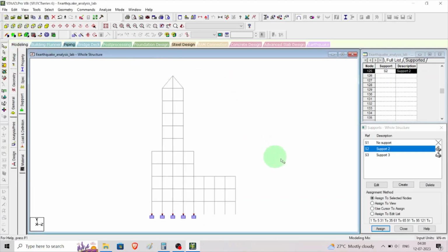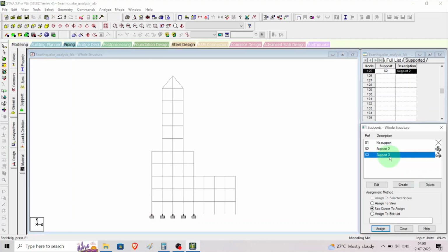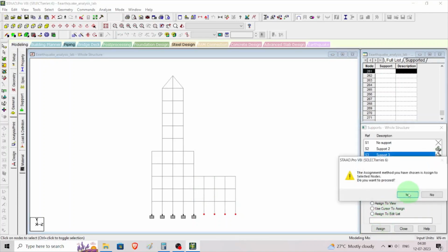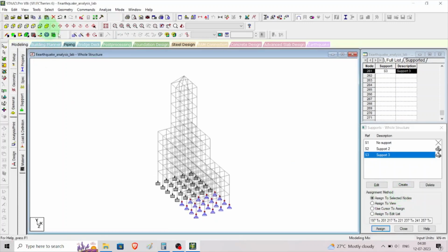Go back to side view, then in the Z direction, then we'll click on the support, then we deselect all the other support, then we'll click select those end of the support nodes, then we'll assign this hinged support, click assign. Yes, by doing that one we are going to get this kind of support. One is fixed, another one is hinged support.